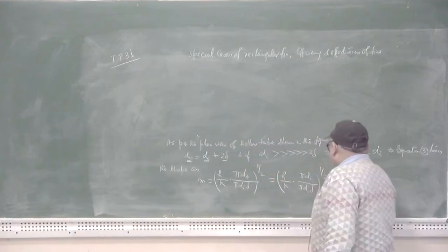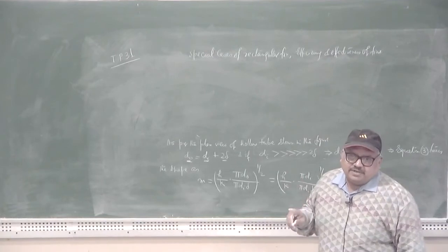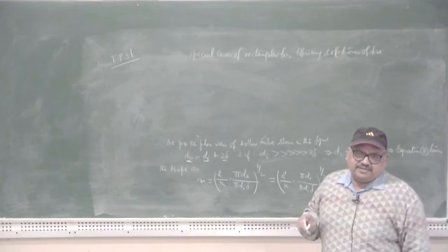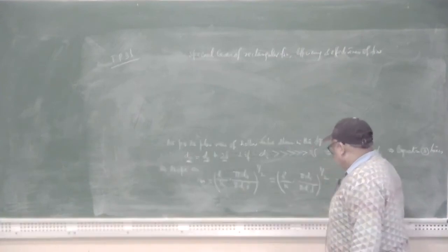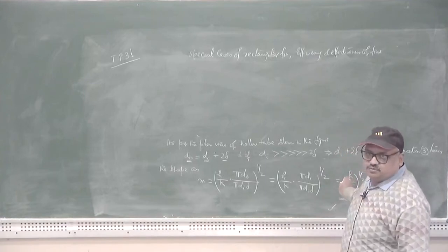So, this equation has importance: when you are using a thermometer well to measure the temperature, the error in that temperature can be calculated by this factor, m equal to h upon k delta raised to the power half.